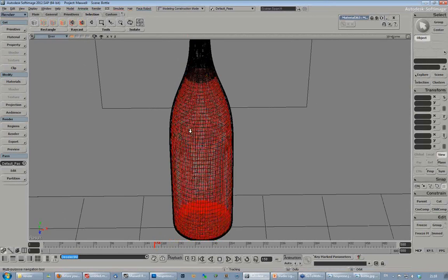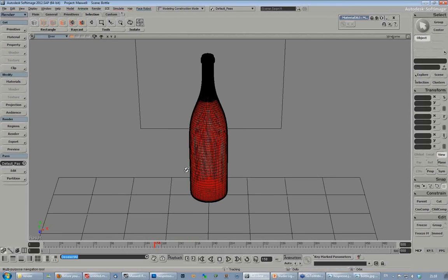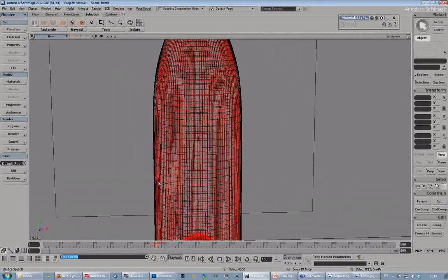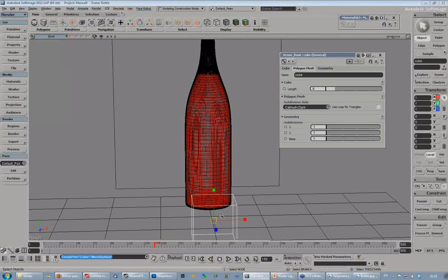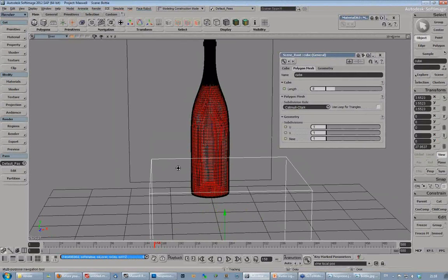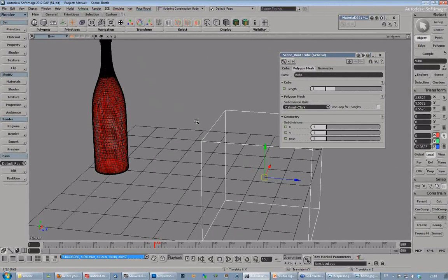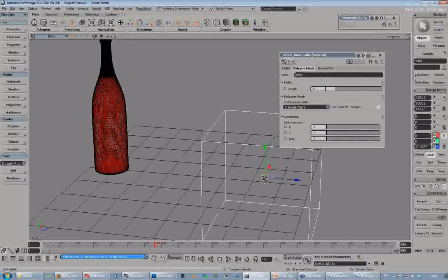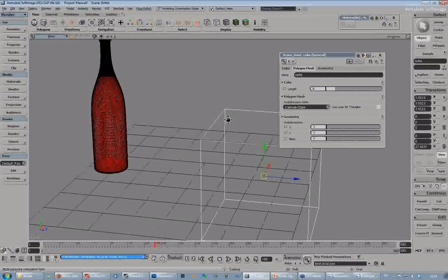Then if the camera is animated, just parent the camera to the bubble, but always keep the camera inside the bubble, because again, Maxwell doesn't know if the camera is inside water, if it's inside a volume, it can't know that it's already inside water. Okay, so imagine this is your cube of water and the camera is inside there. So with Maxwell it sends out rays both from the emitters and the camera. So if a camera ray goes from the camera outwards, it just knows that it's sort of exited water, but it doesn't know that it's inside the water.